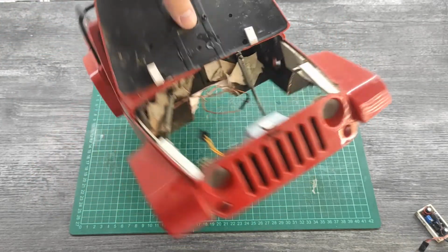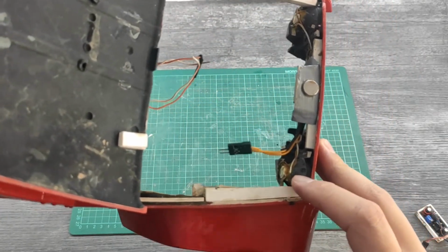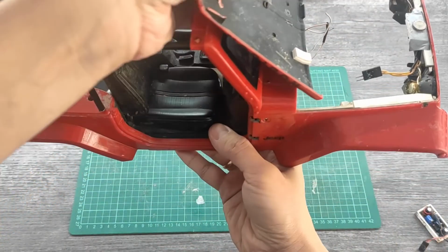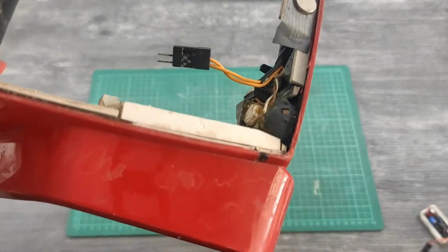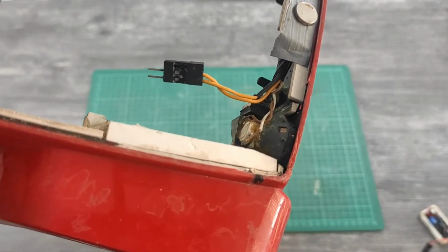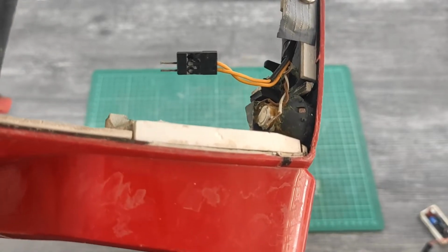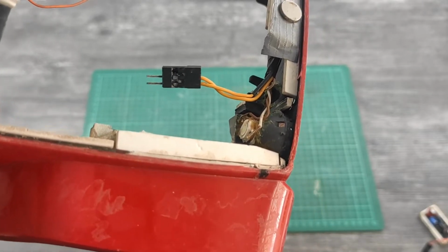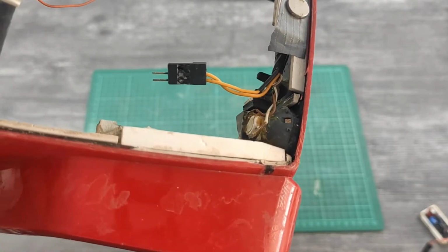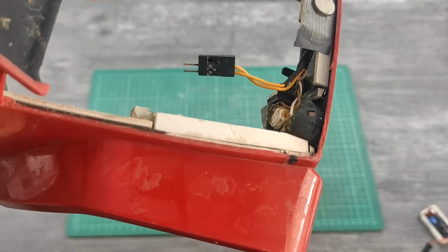In this build I'm using a 1 watt LED. It's a high power one, so if I just connect it directly to the battery, it will burn, as they usually do. On full power, this diode consumes about 300 milliamps, so it's a lot of amperage, and it also heats quite heavily when on full power. So it needs some kind of radiator installed, and